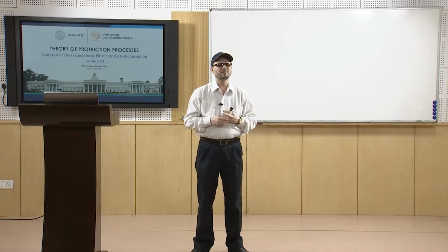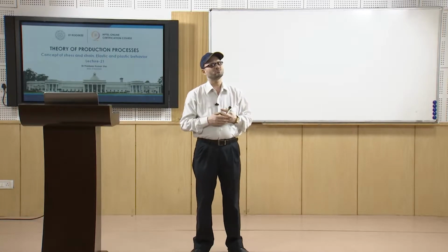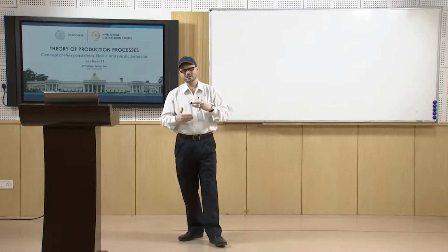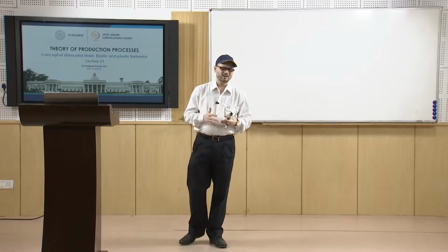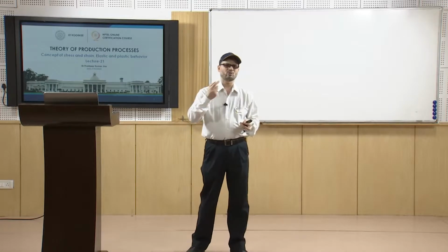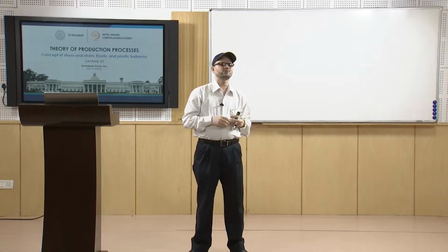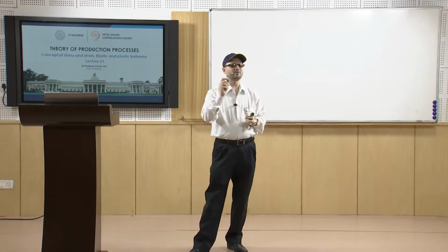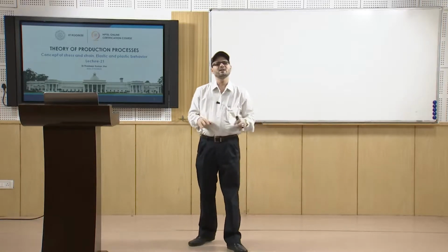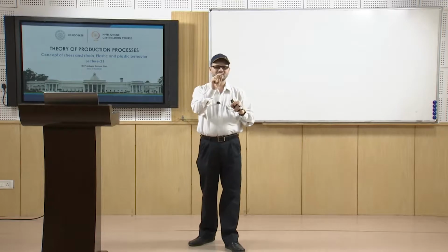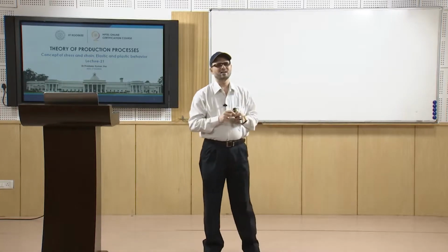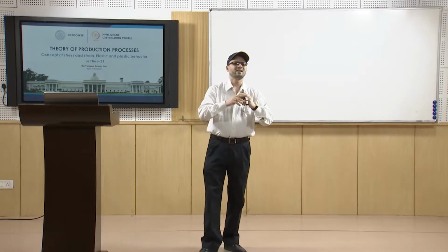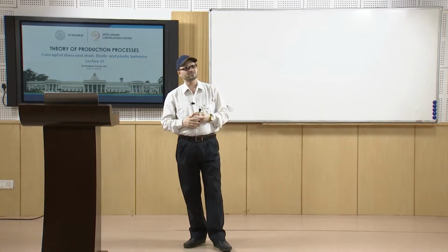none of the materials you will find as continuous, homogeneous and also isotropic. Continuous means there is no void, but that is not the case. You will have micro voids, you will have vacant spaces, you will have inclusions. So it is not continuous if you look at the very micro scale, but once you go to the macro scale it is not the case. So we feel that this is continuous.